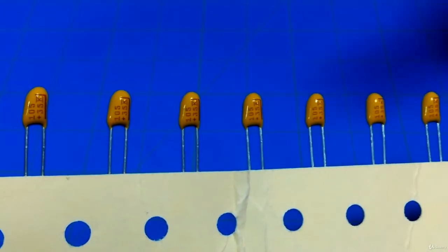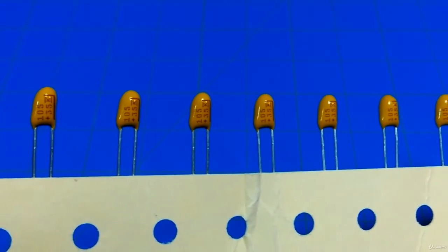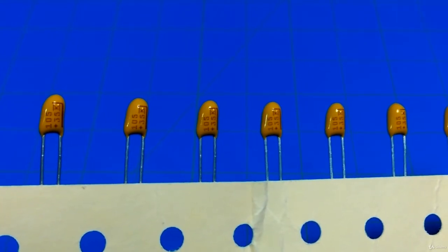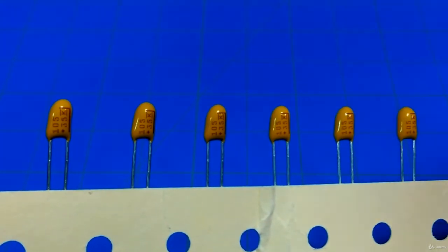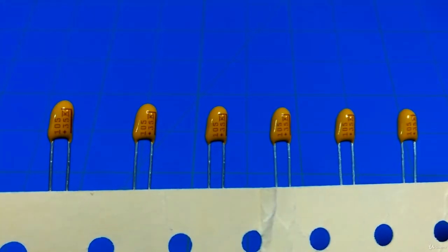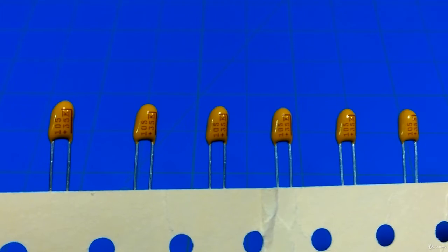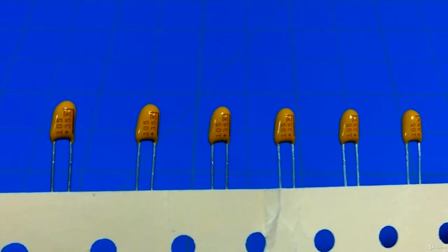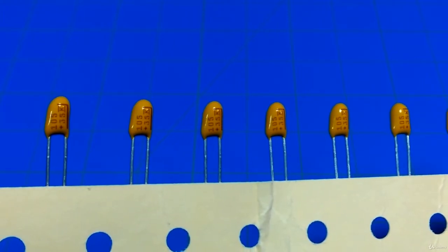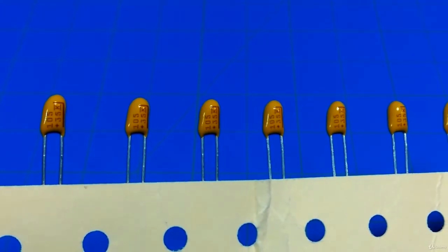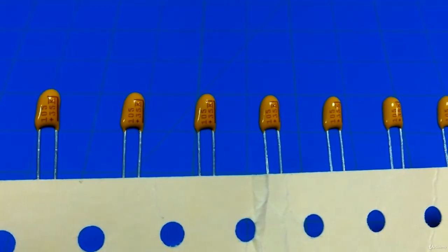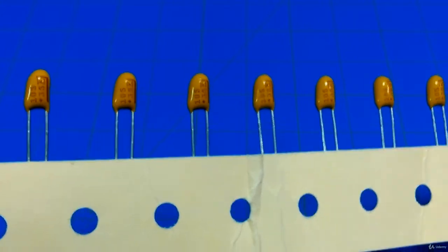And you can see there's 35 on here. These are 35 volts, right? And then you can see the value is 105. These are actually 1 microfarad. When you do the math and do the little encoding, it's 1 microfarad. All right, but I'll show you how to do that. So these are dipped in resin, and these are really good in power supplies. You're going to see these in a lot of power supplies on the inputs and outputs, and they have good properties for that. But these have kind of been overrun by ceramic capacitors as well, because they're low cost. All right. So anyway, those are tantalum.